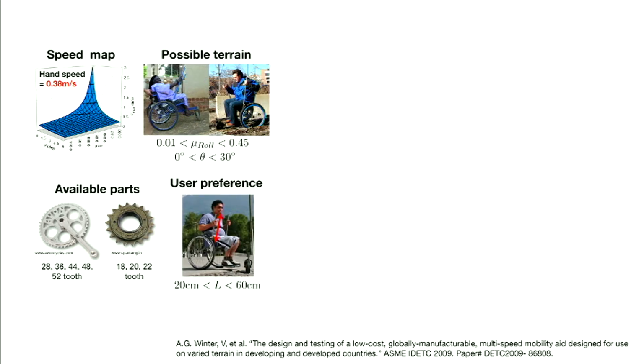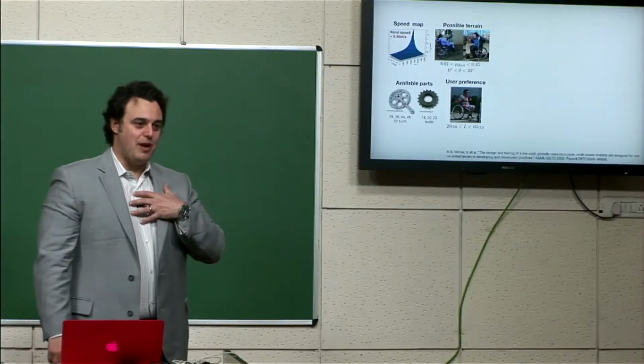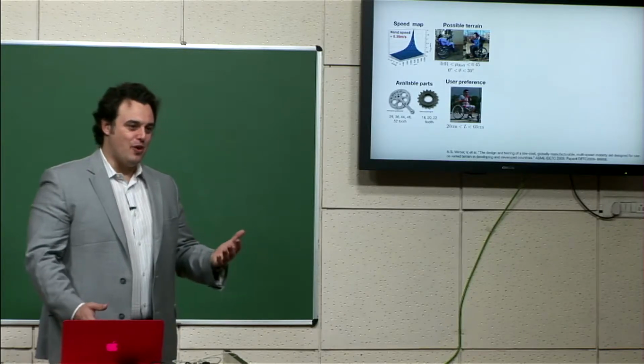And then finally, we had to understand how big the user is and how much of a range they could reasonably grab with their hands. Because somebody can't grab a lever way up here, and even though it's a long lever, you can't push very well with your shoulder. You're strongest doing a bench press motion. And if you go much above your shoulder height, you get a lot weaker, right? So really it's from here down that we could figure out. And I had to realize that this is a guy in Guatemala. If he was standing next to me, he'd probably come up to here, right? I'm a pretty tall person. If I design just around myself, the chair's probably not going to work as well for a guy like that because he's shorter.